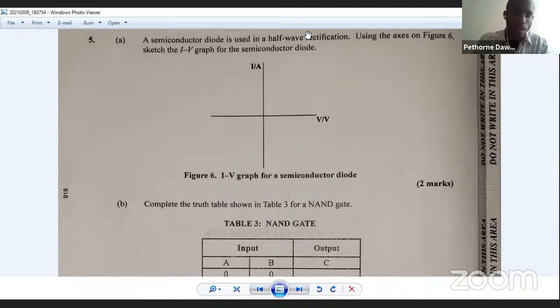The downward half cycle gets cut off, so you just have upward pulses with a gap, and that is the making of rectifying. Rectification is simply converting alternating current to direct current. You need diodes to do that, because diodes prevent the two-way flow. Then you have some fancy working out where you take the half that was cut off and flip it so it goes the same way, but we're not going to get into that. Just know that the diode is a one-way flow valve for current.